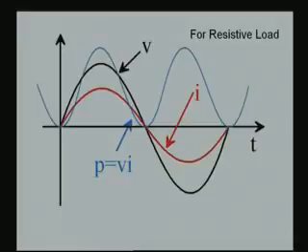So, you see it is a sinusoidal waveform, the blue colored waveform, the power waveform. It is shifted up, it does not have any negative component in this case, it has an offset and it has a frequency which is double the original voltage and current waveforms. Of course, we will come to the mathematics of that one later on, much later, but you try to understand the basic concepts graphically first. So, this is the power wave shape.